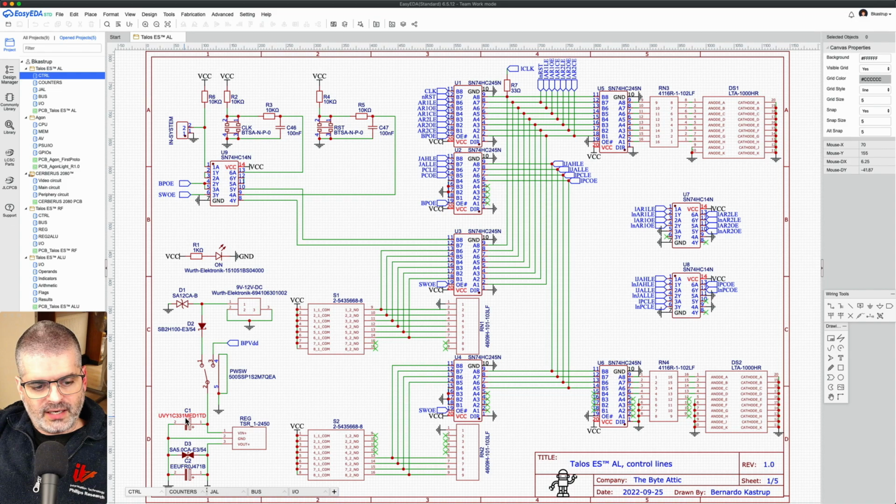And then you can buy this capacitor. I give the part number here. They are available at Mouser and everywhere. And it will fit in the same footprint. No problems there. This is a 330 microfarad capacitor rated for 16 volts. And at 12 volts, 330 microfarad will have more or less the same power delivery as the capacitor I was using previously there, which was rated for 6.3 volts.